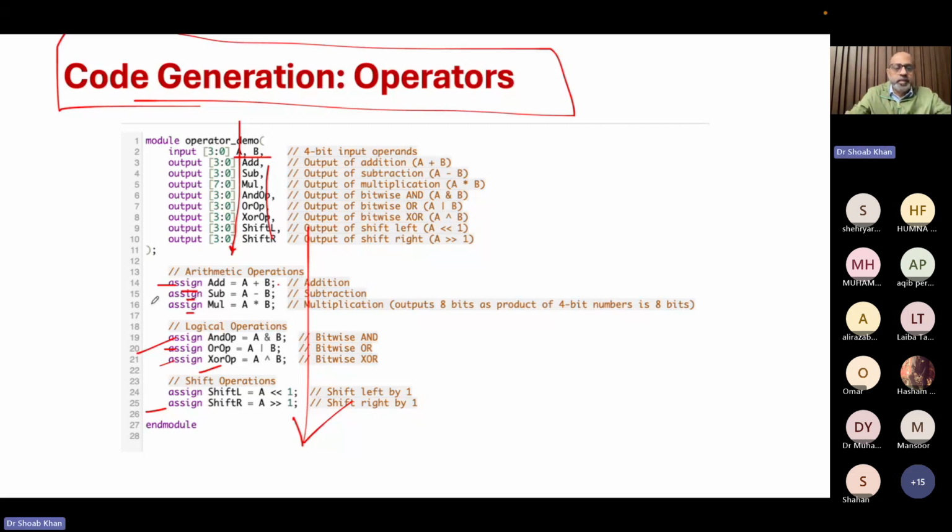Okay, definitely if there is an add, you can use add here, a minus b plus add. The add will be computed, and then you get a subtract. So you can use a variable of type wire as many times as you want on the right hand side, but you cannot on the left hand side. There has to be only one assignment.